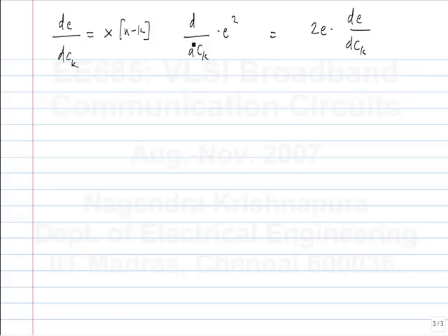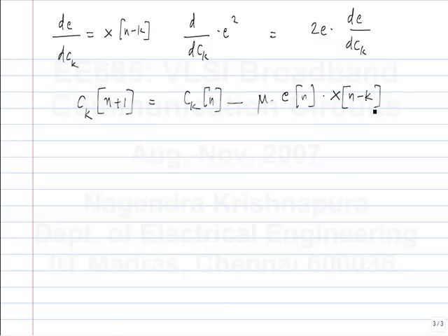I kind of change the indexes and probably confuse the symbols, but I'll use n for time. I think that's best. For every coefficient you will have this. The equation can get kind of confusing because you have too many subscripts and the time variable also. But the idea is the error has to be multiplied with whatever the coefficient is multiplying. Okay. There is a coefficient for some value, some quantity. So in this case, x of n minus k is what is multiplying Ck. So to update Ck, that is the value that you are concerned with. Okay, that should be multiplied with the error, and you need to update the coefficient like this. Okay. And for every coefficient you do this.